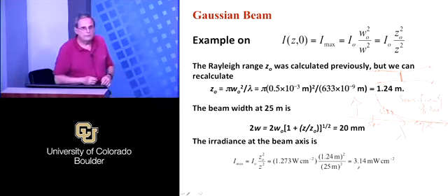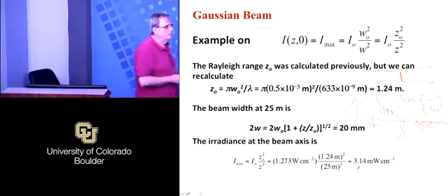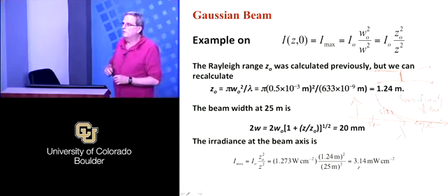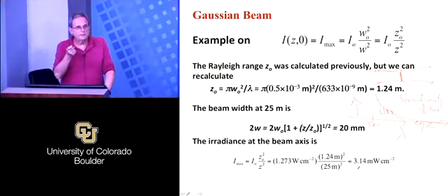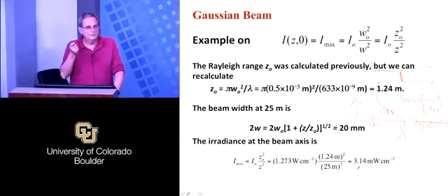One of the reasons why 1550 nanometers was chosen for fiber optics is that at 1550 nanometers, if you have several milliwatts in the fiber core, it's eye safe. That was one driving decision. Another one was dispersion.